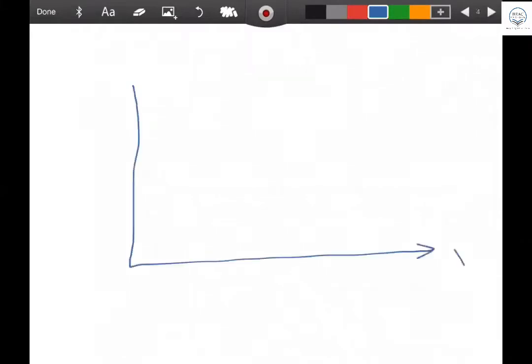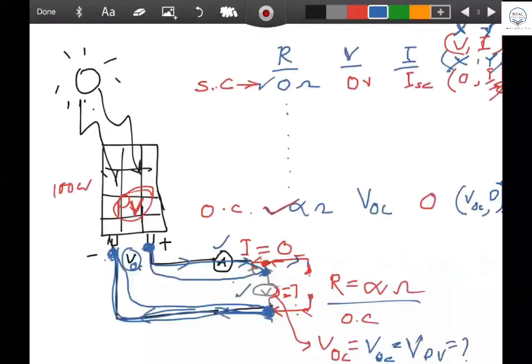Sir, I want to ask a question. Yes, sir, please go ahead. Sir, if there is no current flow, will there be any voltage? Yeah, if there is no current flow, that's what I show you. If there is no current flow, it's open, then straight away the voltage at these two terminals will be the voltage of the battery terminal.